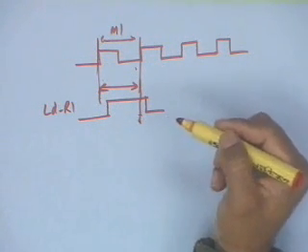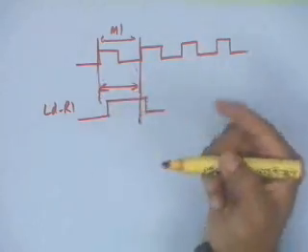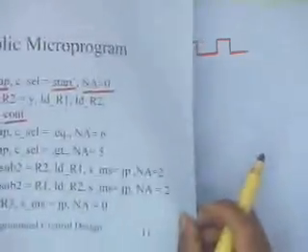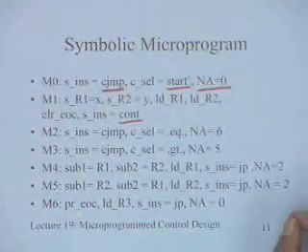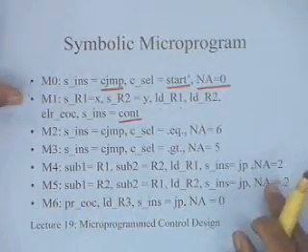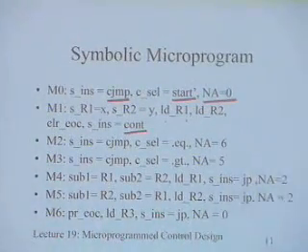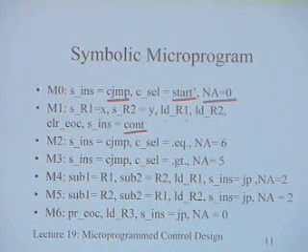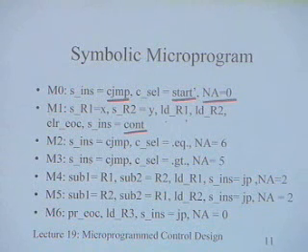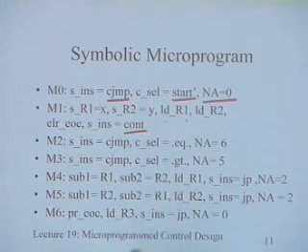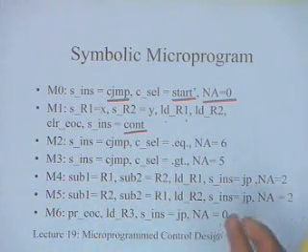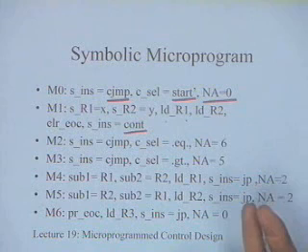Of course, the issue is why at the end? Why can't we do it at the beginning? We will clarify this next time when we come to the next instruction, why this is required. So now, if you consider your data path, the output of this is going to the comparator. And my comparator will require some time to compare. The two most important delay elements as far as my data path is concerned are the comparator and the subtractor.